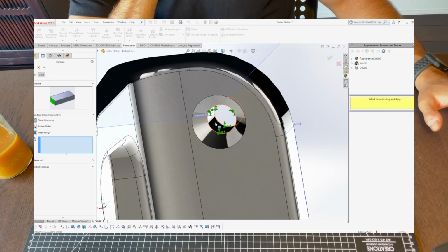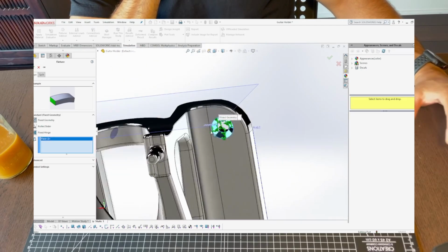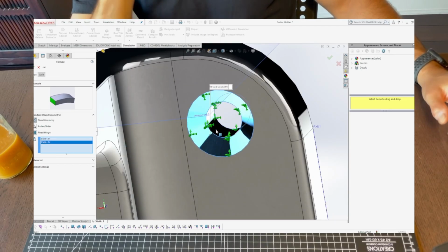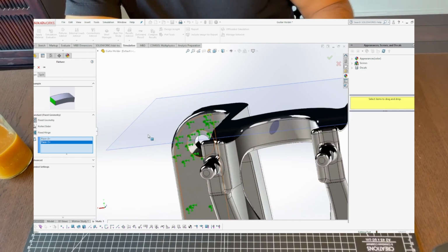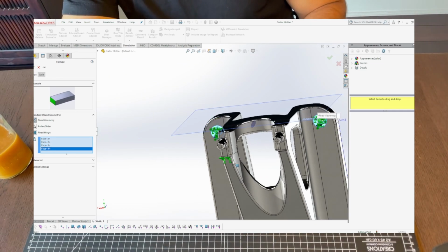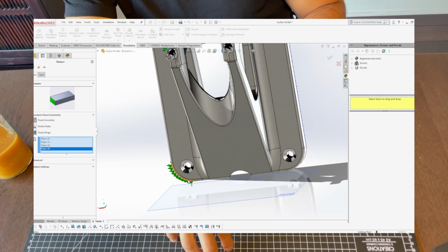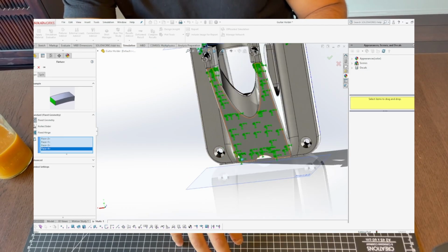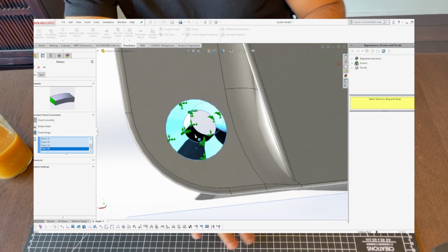So when I was designing, I actually had to go back for this. I made sure that there were separate faces when I was designing the part that I knew would be holding the guitar. So any interfaces where the guitar will be touching or I'd be screwing something in, I could define them there so that I could actually pick them out easily and identify them later on and attach them to certain things like load bearing or fixtures.